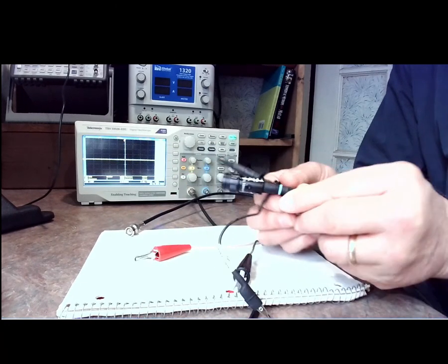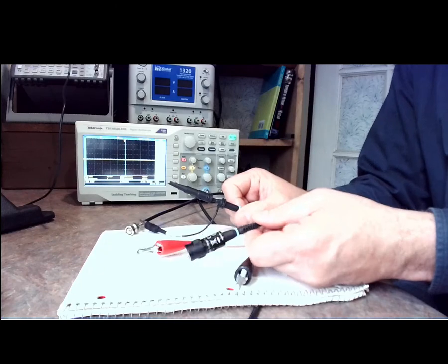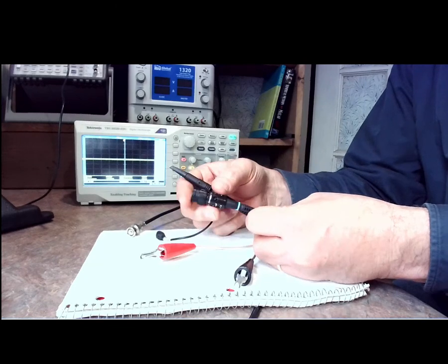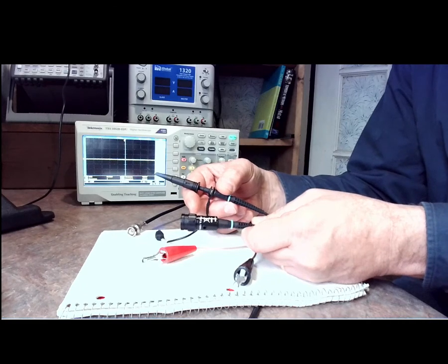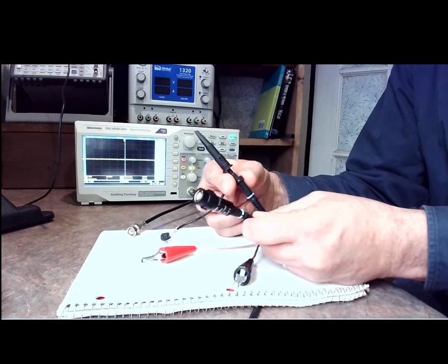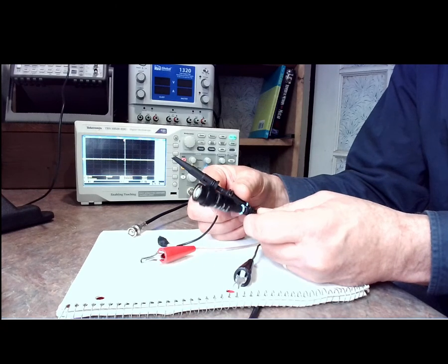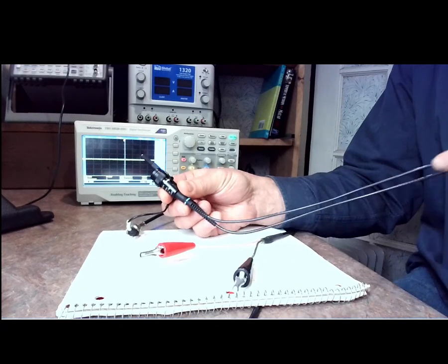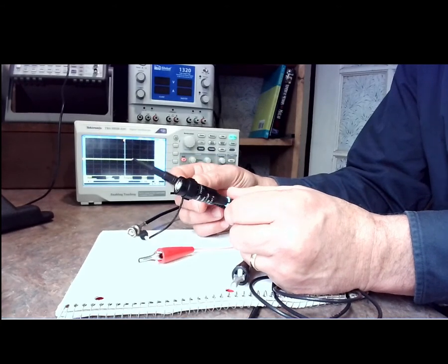This connector is a special connector designed for an oscilloscope, and it actually has a resistor in it. It has attenuation in it, so this is fine to use for an oscilloscope, but you certainly don't want to use this type of connector for connecting a function generator to supply a voltage and a current into a circuit, because there's attenuation and special circuitry within this that's going to affect what you're trying to inject into your circuit.